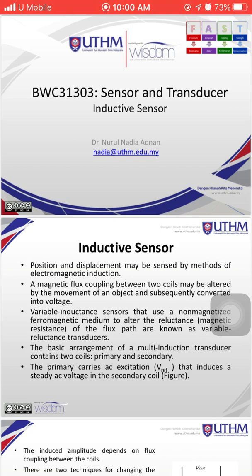Another advantage of the inductive sensor is that it is a non-contact measurement of displacement, distance, position, oscillation and vibration. So they do not contact the object. It is suitable when we need to make a measurement with high precision in harsh industrial environments, such as pressure, dust or high temperature.